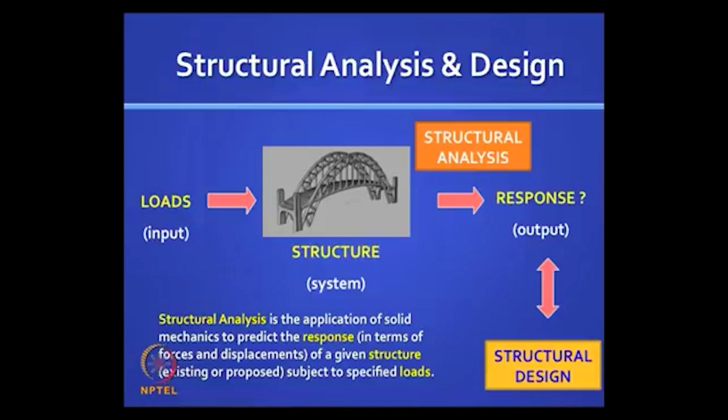And along with structural analysis we have structural design. Your real objective is to do structural design, but in order to do design you need to do analysis. In design we proportion the structures, we identify the materials, and you need to have some initial proportions to do analysis in the first place. So it is an interactive process, and there are some requirements of any structure.